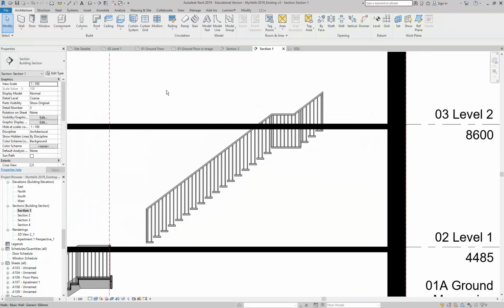So what's the minimum height above a stair? Okay, you're close. All right, so what's the minimum height of a ceiling generally? That would be an uninhabitable space. Standard thing, so it's 2100. Yeah, you'd think so. So that is right. 2100 is normally the minimum. Yeah, 2400 for living spaces. But for non-habitable spaces, bathrooms and kitchens, you can go down to 2100.